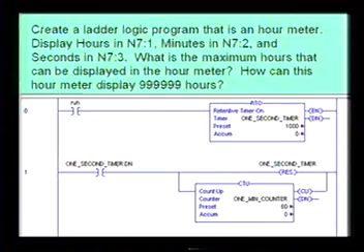Unlike the RSLogix 500 integer values, which can only go up to 32767, the integer values, or double integer values here, can go up very high. So making an elapsed time meter in RSLogix 5000 ControlLogix is a lot easier. So here I created a retentive timer on. When the run turns on, this bit turns on, this retentive timer turns on, and it's a 1 second timer.